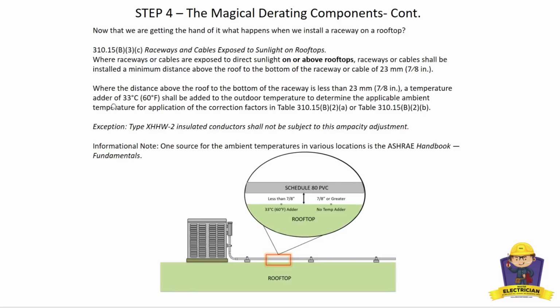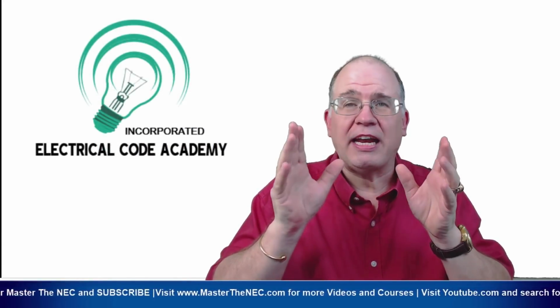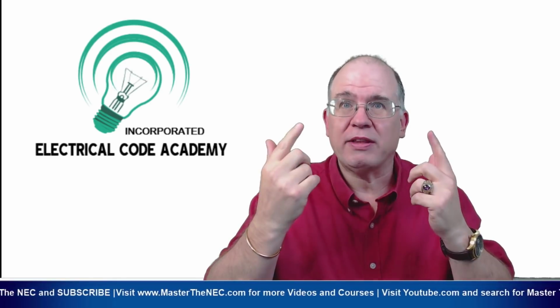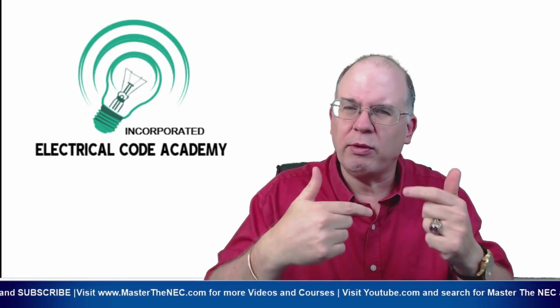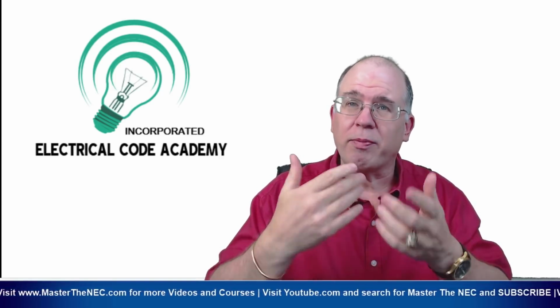A temperature adder of 33 degrees C or 60 degrees Fahrenheit has to be added to the outdoor temperature to determine the applicable ambient temperature for application of the correction factors in 310.15(B)(2)(a). Okay? All right, so let's understand here. With this adder, I've still got an ambient temperature. I still have to know what that ambient temperature is. We have to do everything that we've done up to this point. Wherever that raceway or cable is located, we have to apply an ambient.